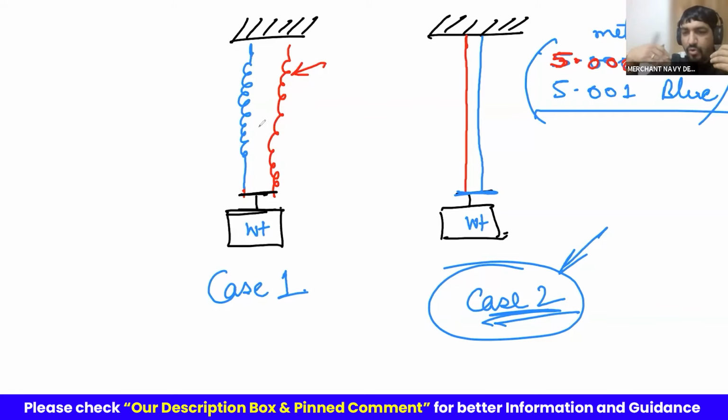First of all, droop is needed because you do not want one generator to be rigid. It says, I will not change the RPM. If the load is more, let it be. I will keep my RPM high. So the other generator will say, you do not want to drop your RPM? Fine, I'm happy with the situation, because the one which maintains higher RPM will take more load. So the generator which was ready to reduce its RPM with the load is happy to give the load to the other one. You take the load, I will not take the load.